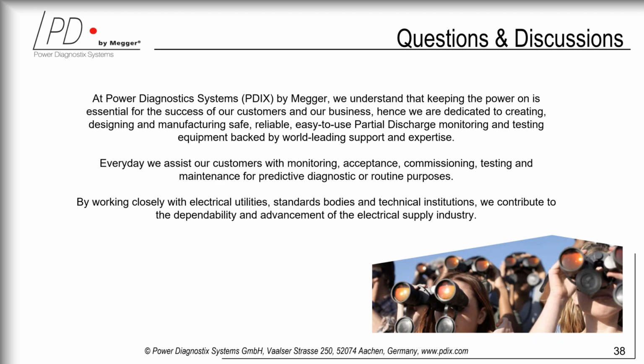With the HFCT, you have the galvanic separation of the output from the input. Some customers prefer to have this galvanic separation on the PD output, and for that reason, you can decide at site, by opening the lid of the box, which kind of decoupling method you choose. There's a switch, a jumper on the box, and you can switch between two different modes.